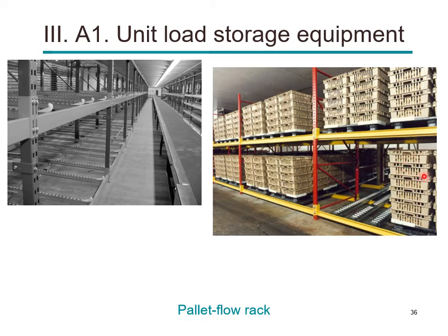You may retrieve, or you can also retrieve from the other end, but the thing is, you don't need your storage and retrieval device to go inside the rack. With the help of this gravity and with the help of these wheels, they come through this side automatically, and when you, for example, take this unit load from this side, all other loads will move again to the front side.